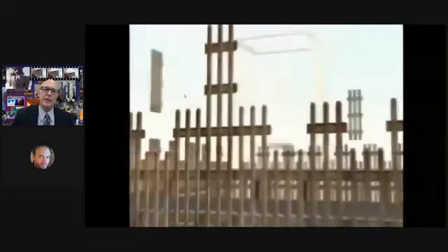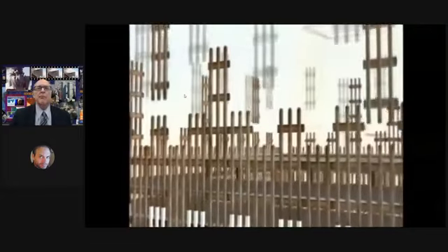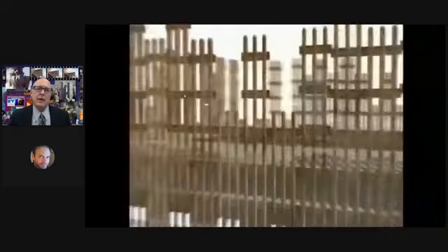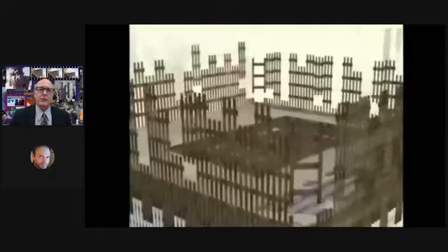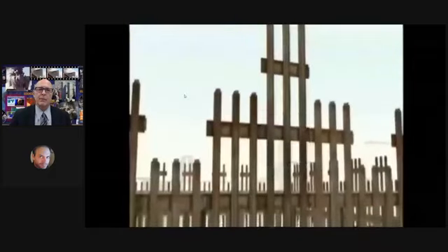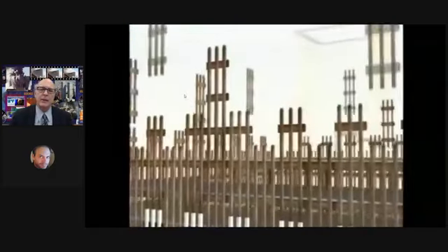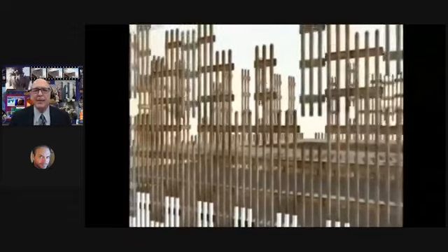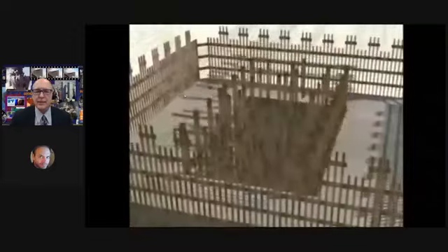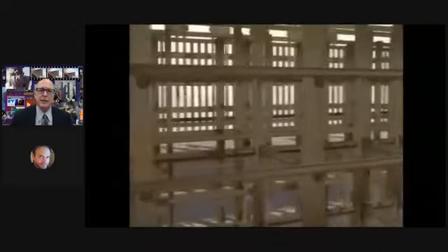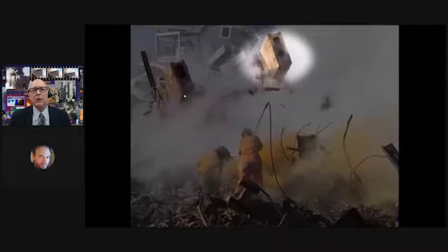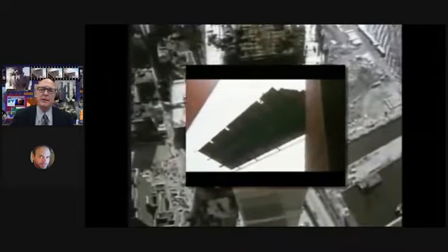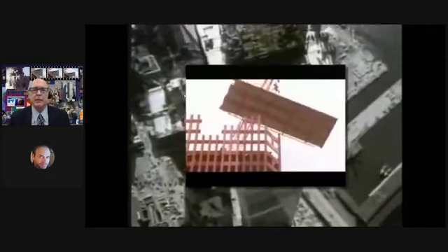What they did with the Twin Towers, though, was move back half the columns to the perimeter in an exoskeleton with 3 vertical welded to 3 horizontal structural members, which were brought and erected in place with cranes and bolted together. Inside, we had a massive series of 47 incredibly dense core columns, which halfway through the structure at mid-height are 22 by 16 inches, and then solid steel at the base.